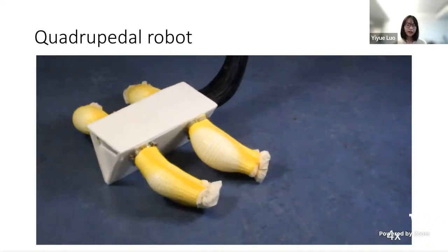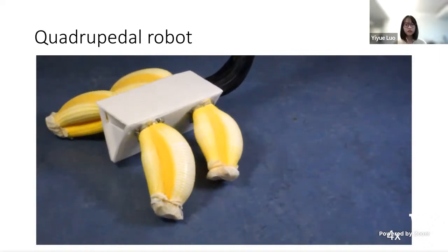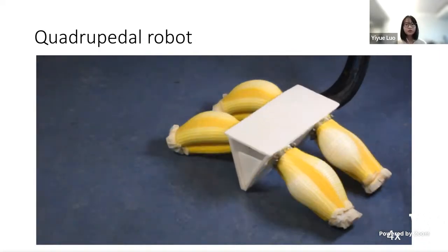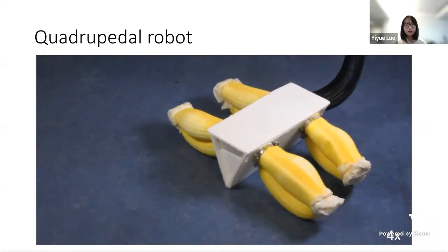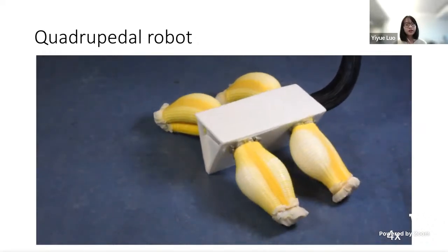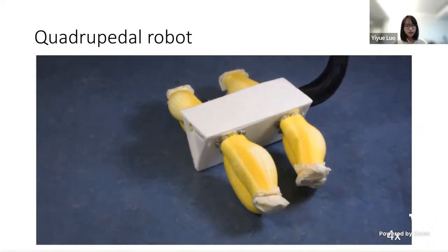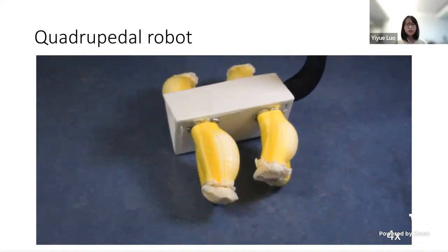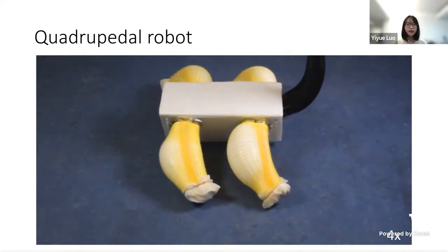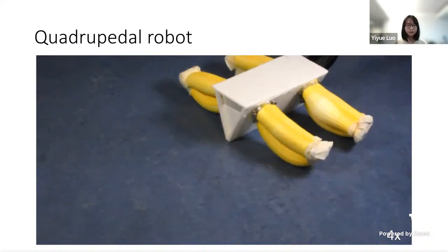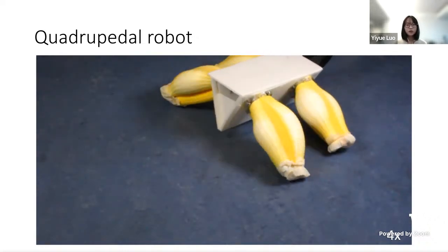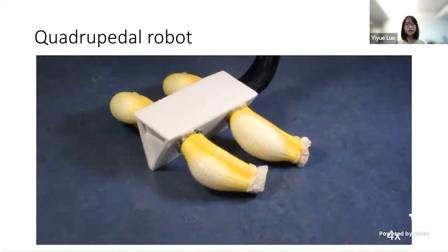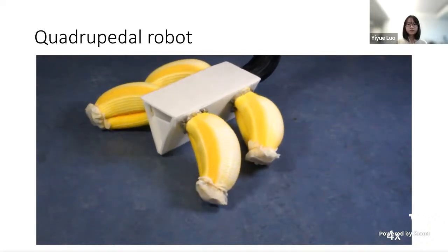Each of the 4 legs here consists of 3 actuators, 2 of which bend forward and backward, while the third one bends the leg upward vertically. So we predefined the motion pattern of each leg. The predefined motion pattern forms a rowing-like motion, pushing the quadrupedal robot forward, backward, or even doing a turning motion.